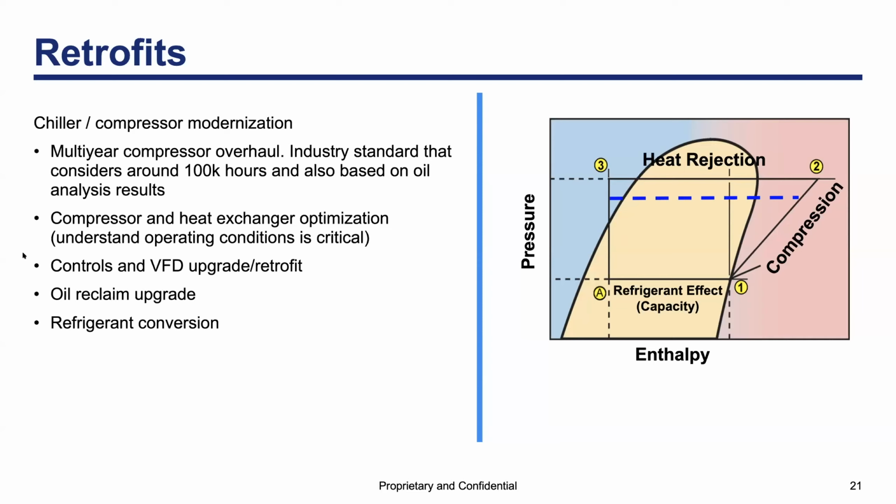And when I talk about limits, keep the following in mind. For cooling towers, confirm what is the minimum fan speed and the minimum flow rate to prevent poor distribution of water and poor heat transfer. For chillers and pumps, confirm minimum and maximum flow rates, minimum requirements at low loads, specifically at low loads, to make sure that the unit is stable.